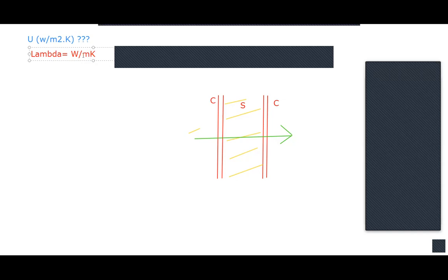It stands for the ability of any material to conduct, to lead heat, so it's different for all materials. So how much energy, how much in watts, goes through 1 meter, let's say, of wall in linear dimension, for a change of temperature of 1 Kelvin.